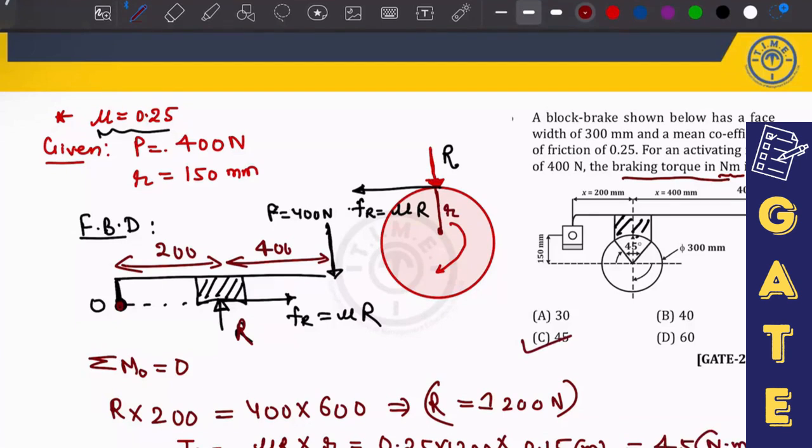So in this particular problem, if you see, the hinge joint is coinciding with the direction of the friction force. That means it is coinciding with the frictional force. But if this point is above or below, then the friction force will also create a moment. So why have we not taken the friction force moment? Because this friction force passes through here, so there is no perpendicular distance.